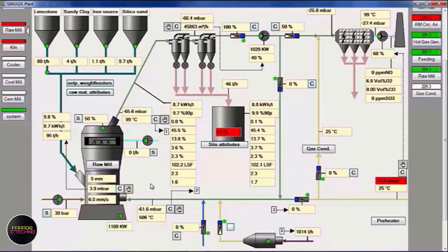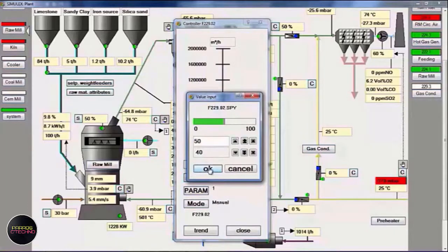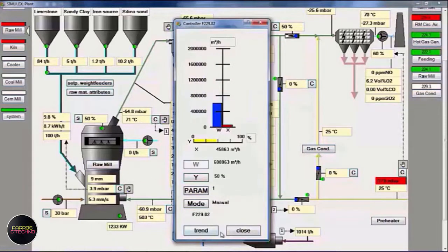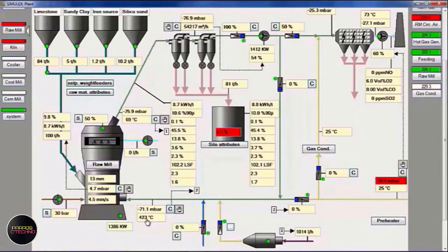The temperature at the inlet is high and the outlet is low, so the mill fan must be increased, because the feeding increases the pull, so that the temperature at the outlet increases and the temperature at the inlet decreases. To control the operation of the raw mill, it is not only the temperature that is expected, but also the volume of air. If we use the preheater system, in addition to the temperature, the volume of exhaust air driven by the SP fan is quite high, so that the volume and temperature are sufficient for drying and grinding of raw materials inside the mill system.